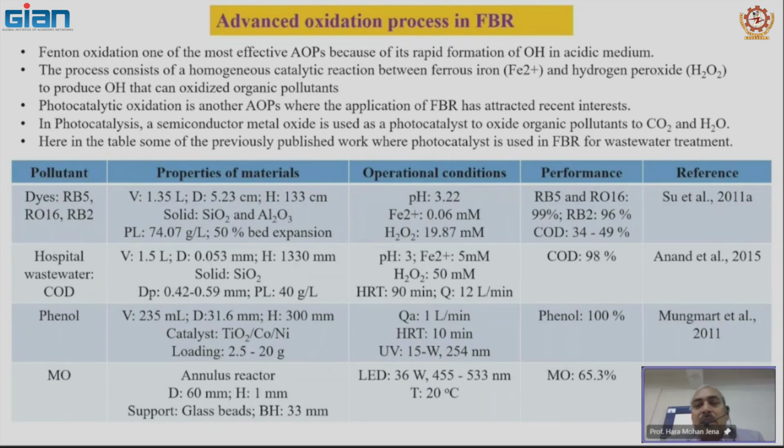Here another table shows the published work in the area of photocatalysts used in the fluidized bed reactor for wastewater treatment. Dyes, hospital wastewater, COD, phenol, methyl orange, another dye. These things are removed, and it is very effective. For phenol, 100% degradation is achieved. COD removal is 98%. Rhodamine blue 96%. Another Rhodamine blue, and 99% is also achieved.